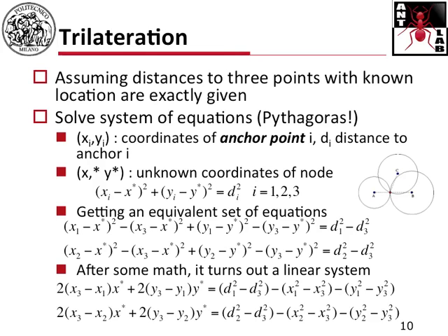Okay. Then you can write down this kind of equation for all the anchor nodes which you have in your system. In case of ideal conditions, so in case these measures here, the di's, are not noisy, so they're perfect, you just need 3 equations to localize one point, which means that you just need 3 anchor nodes to get the position of one point.